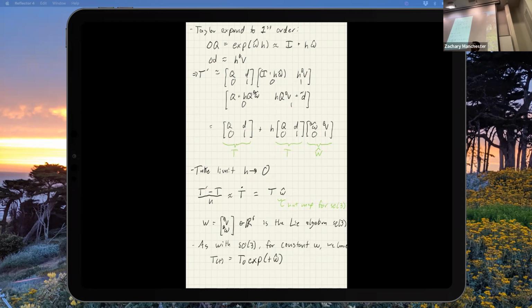It means you're writing the velocities in the inertial frame. So you can do that. But what that corresponds to, if you do this the other way, is having all the velocities in the inertial frame. So if you were to write down omega in the inertial frame instead of the body frame, and in this case V in the inertial frame, you would end up with the kinematics the other way. And that's why, and you will see that in books.